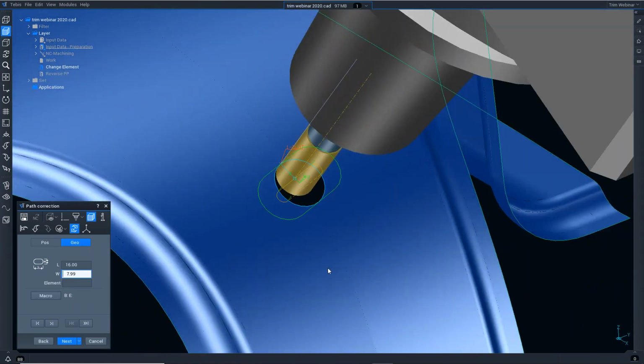So the advantage of this is quite a lot of design will have this as a bolt hole so that parts mate perfectly and we can just drop a screw straight through there. Obviously, in the real world where we're manufacturing components, we can have deformation of parts, we can have shrinkage, or we could just have a general losing of sizes and dimensions across vac formed parts or molded parts. So what we could do is add a slot into this now, so that any mating part that's screwed to it, we've got a little bit of adjustment space, a little bit of wiggle room to be able to get a screw in. So that's quite handy that although it is a circle, we don't have to define it as a circle. We can define it as a slot or a rectangle or anything we need to.